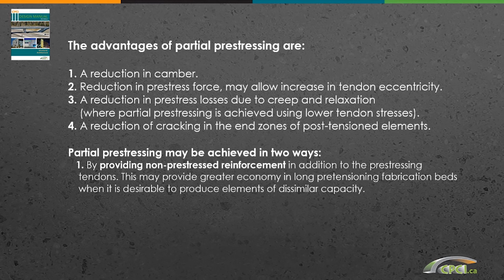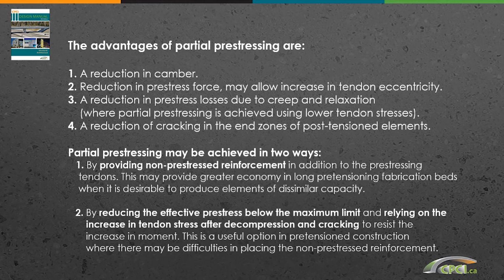Unless you have some kind of a condition that you cannot run away from, maybe the live load is definitely going to be achieved, like snow load, for instance, that we know that's going to happen. And also if the cracking conditions are not desirable at all, if the exposure is critical, if it's an architectural feature that cannot be marred by a crack under any condition, then you check the section as a fully pre-stressed concrete, not partially pre-stressed concrete.